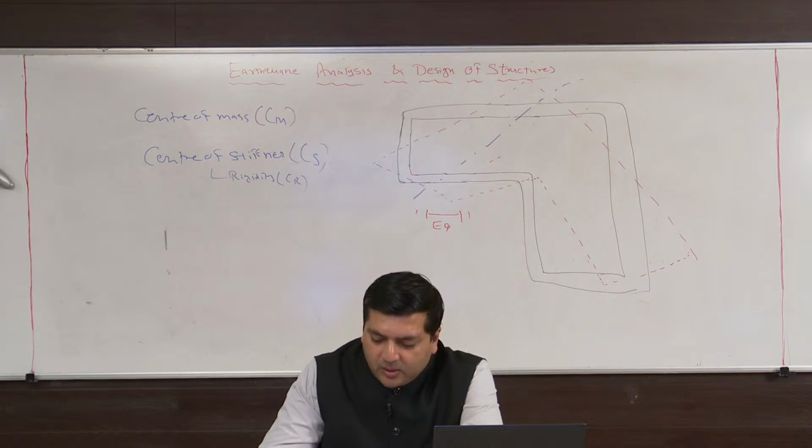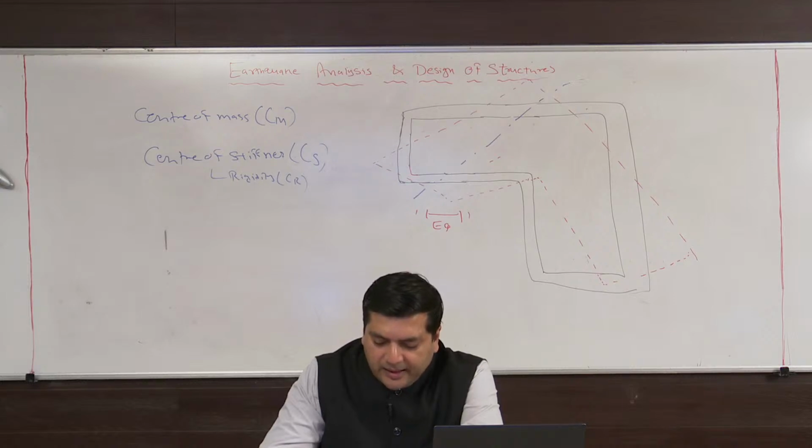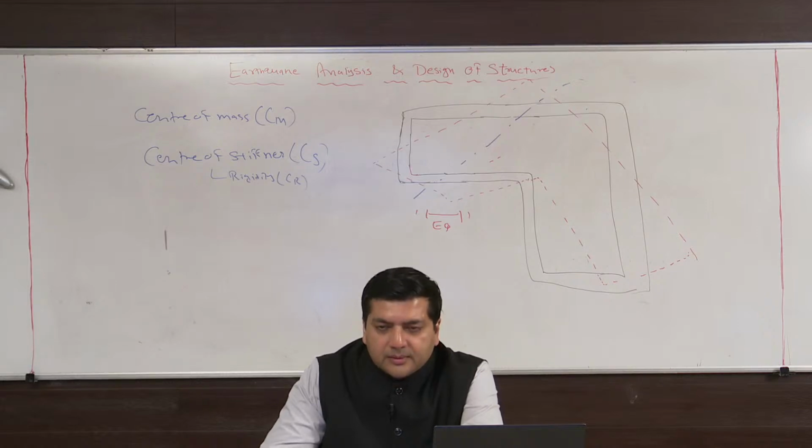The building as a whole or its various blocks should be kept symmetrical about the axis. Full stop. Asymmetry leads to torsion during earthquake and is dangerous.